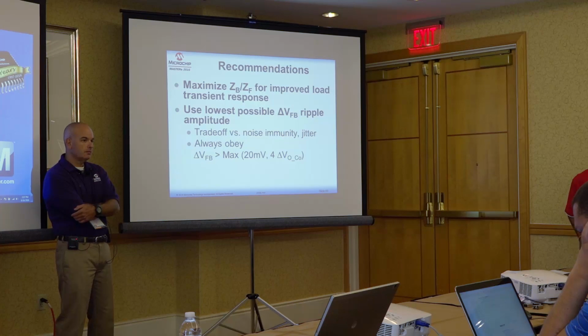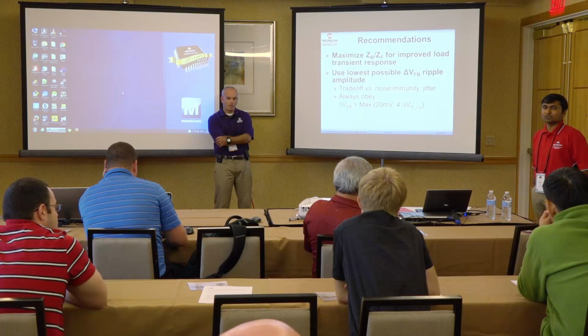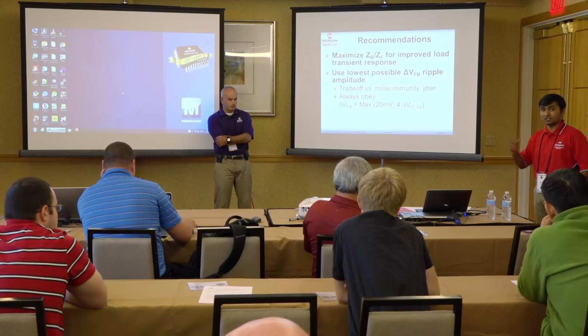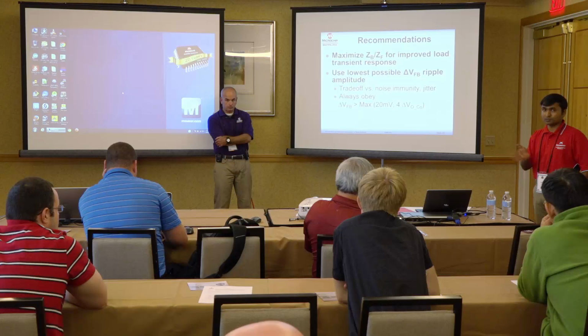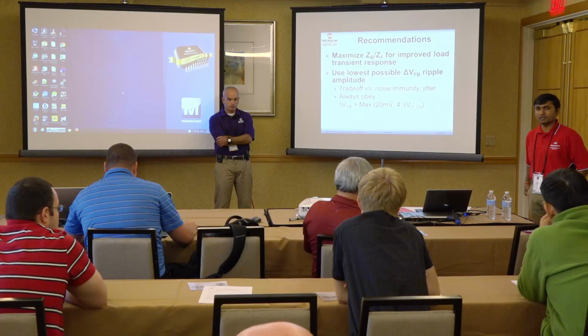So no matter how big the output capacitor is, it won't affect transient? Yes. During startup, you may enter into inrush current limit, and the start is slow if your output capacitor is so big, but other than that, it doesn't affect.